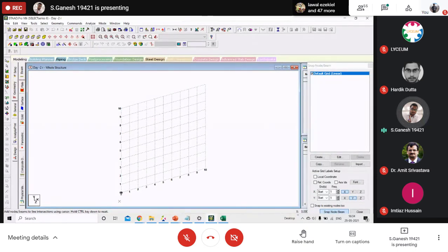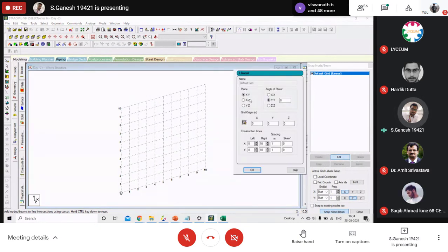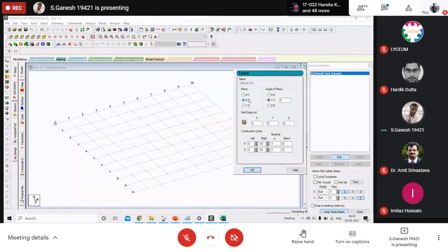This is what we discussed in the last class, till the Outlook interface, how you did it. Click on edit. The very first step I do is XZ, so I change from XY to XZ. Then you need to adjust these grids. If you want to adjust the grids for a decimal value, you can do that, 0.55 also. But I'll just keep it as 1 meter only.